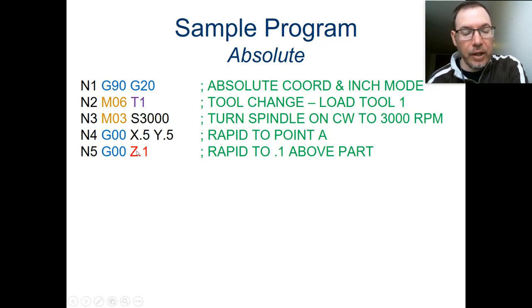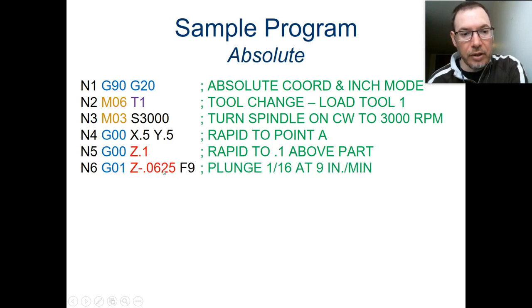stop at that point. Now, our very next command is then going to be to continue on down into the part. So you're not going to really see a pause, but what you will see is a change in speed. So it's going to come down very quick to 0.1, and then when it gets to 0.1, it's going to slow down and then continue down in an actual cutting motion.